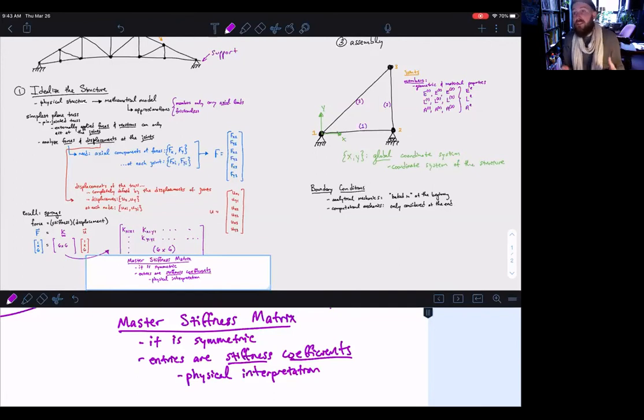Here we have the simplest structure: a 6x1 vector equaling a 6x6 matrix times a 6x1 vector. As you make your physics more complicated, as you have more and more nodes, this matrix increases in size significantly. And the goal for us right now is to figure out what goes into this stiffness matrix for the particular problem that we're solving.